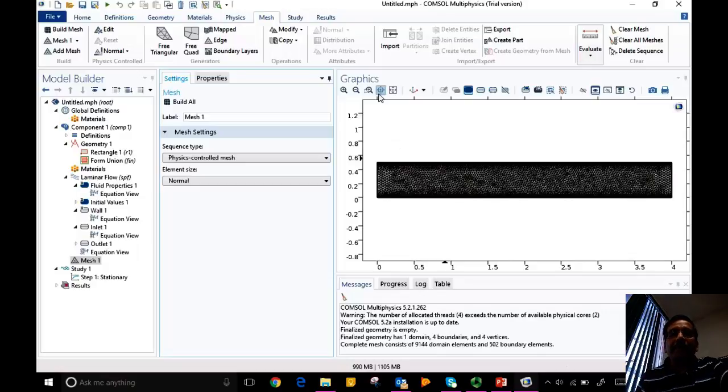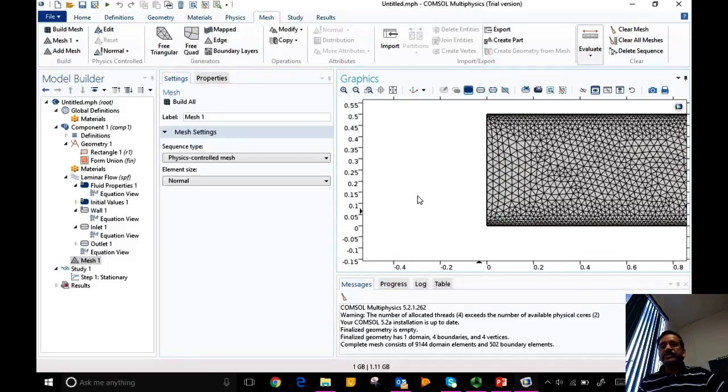And if you blow it up, for example, you can zoom it in, you will see a structure in this mesh. Okay, they are all triangular meshes, right? But what do you see? You see that the spacing is much smaller. The grid sizes are much smaller near the wall. And also, it should be smaller near the entrance, and you can maybe make it bigger as you go in. They didn't do it here. Why do you think it is closely spaced in this region? Because that's where you have sharp velocity gradients, right? The numerical error comes from approximating the gradients with finite algebraic expressions.